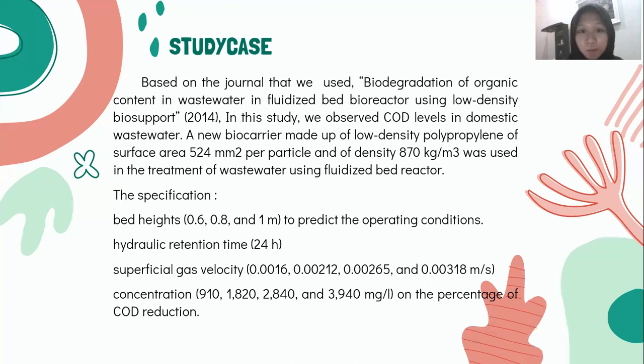In this study, we observed COD levels in domestic wastewater. A new biocarrier made up of low-density polypropylene of surface area 524 square millimeter per particle and of density 870 kilogram per cubic meter was used in the treatment of wastewater using fluidized bed reactor.